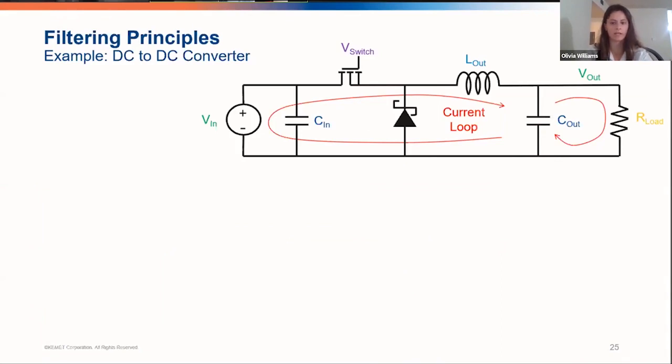And then on the other side, we have C out, which is also integral to the switcher operation. It's our filtering cap, and it's basically charging and discharging on the switching frequency so that the voltage stays nice and constant with only a slight ripple. So a lot of care has to be taken when choosing this type of capacitor as well, so that the parasitics will have as little impact on the efficiency of the converter as possible. And of course, we also use inductors here to help on the filtering as well. Use them there in combination with your C out capacitor.